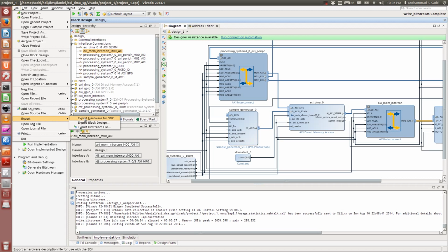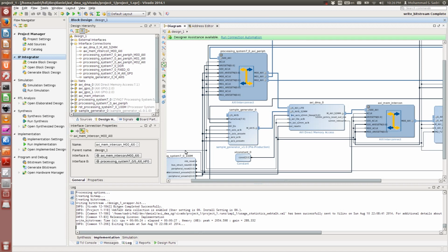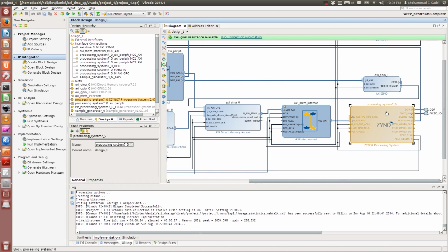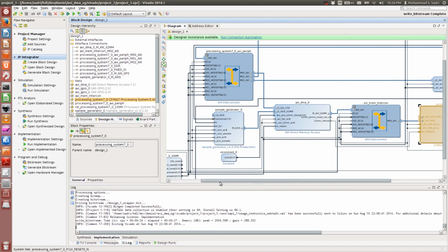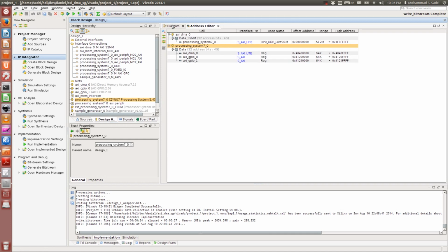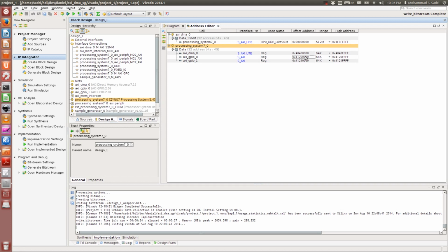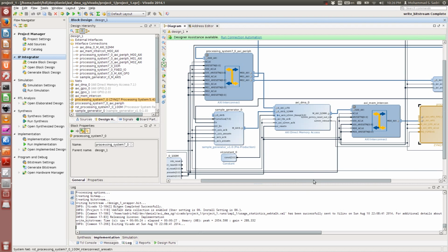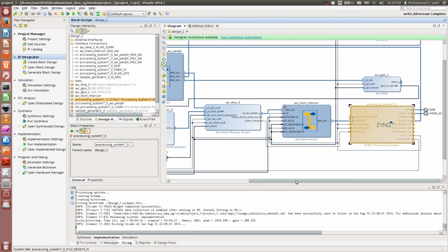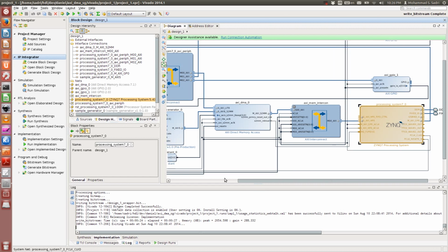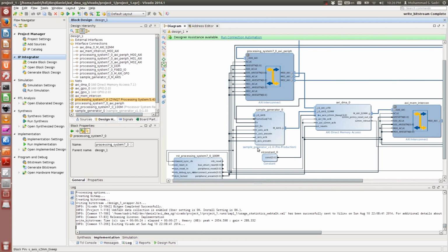I described that the hardware contains a lot of parameters and important information that are used during software development. These parameters are mostly related to initialization of the PS, and the important information that I am talking about is related to how you have configured the components that you have here. For example, what are the address ranges through which the ARM host can access different components that you have on the PL. I have described this in detail in previous videos, so I continue.